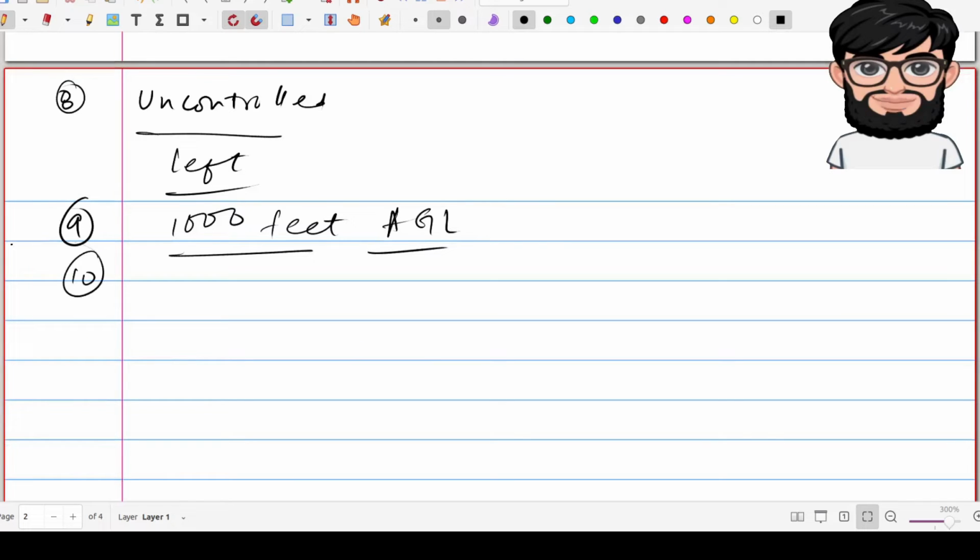Then what recommended entry and departure procedures should be used at airports without an operating control tower? If you do not have ATC, a pilot should plan to enter the traffic pattern in level flight. Always remember that.